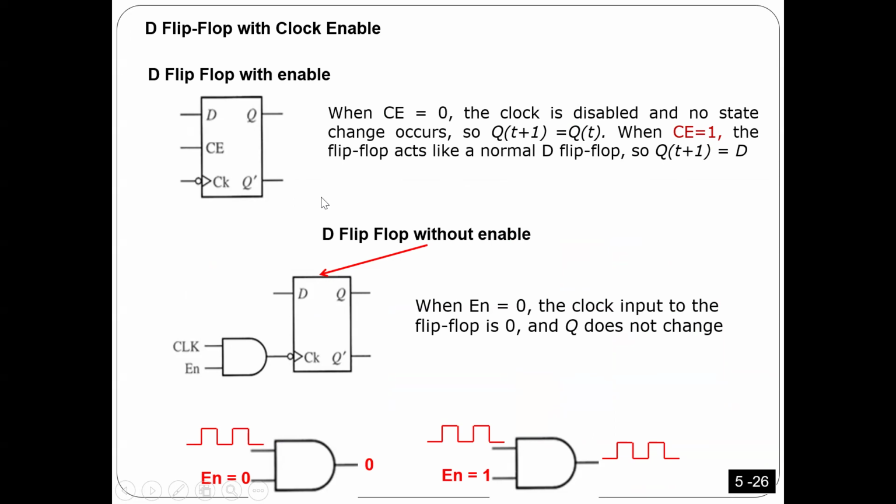One of the things also some flip-flops may have is enable. So some flip-flops have enables. In addition, again, I told you guys, in the case of D flip-flop, these are the basic ones: D, Q, and Q prime. Sometimes we add clear, sometimes we add set, and sometimes we also add enable. So that's why in the coming lab, you need to read the data sheet to see what the inputs of the flip-flop are. So you can design it to add enable.